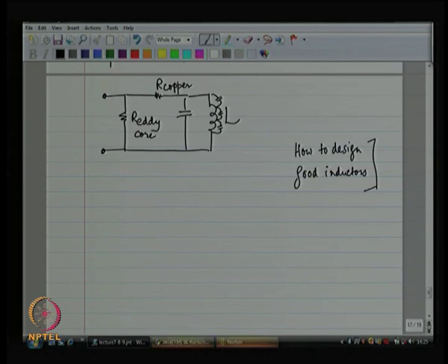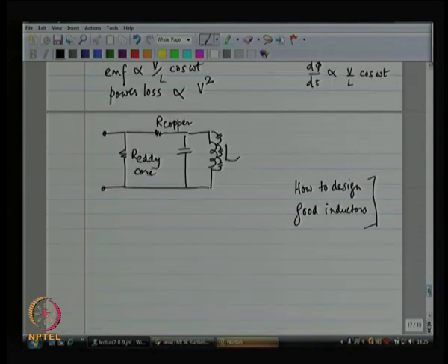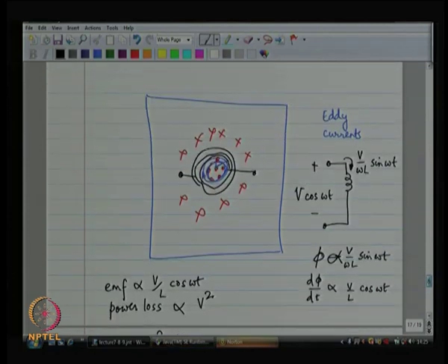In addition, the inductor is not really a pure inductance. You have a piece of wire hanging on top of a substrate, so it looks like a parallel plate capacitor as usual, and that is also part of the model. Not only that, to make things worse, each turn of the inductor is coupled to every other turn through side wall capacitance.